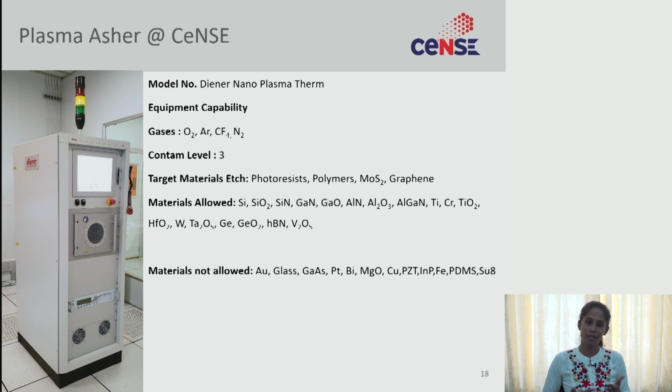If you go for etching without an O2 descum, whatever resist particles are there might act as a mask for you. So to avoid that, what we'll do is, with a low power oxygen plasma, we'll do an O2 descum. At that time, if there is any kind of photoresist or any particles, it will get rid of it, and then our etch region will become clear for etching.